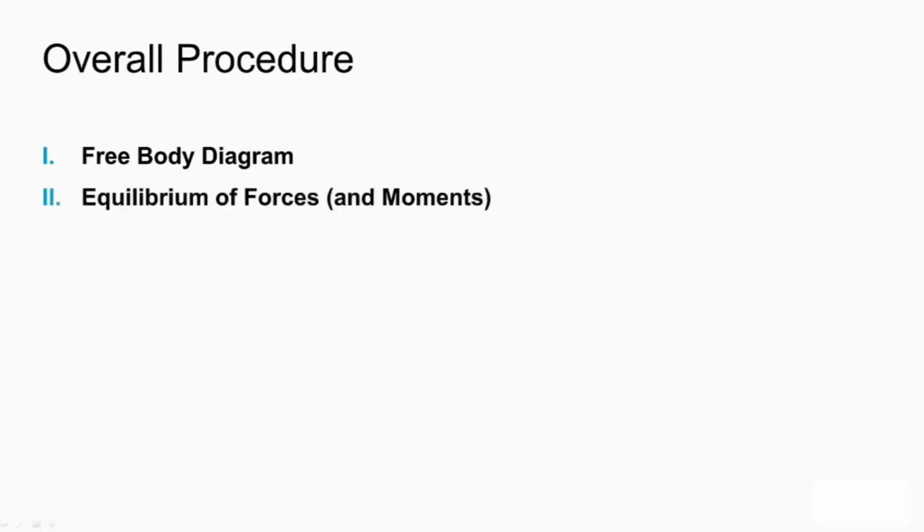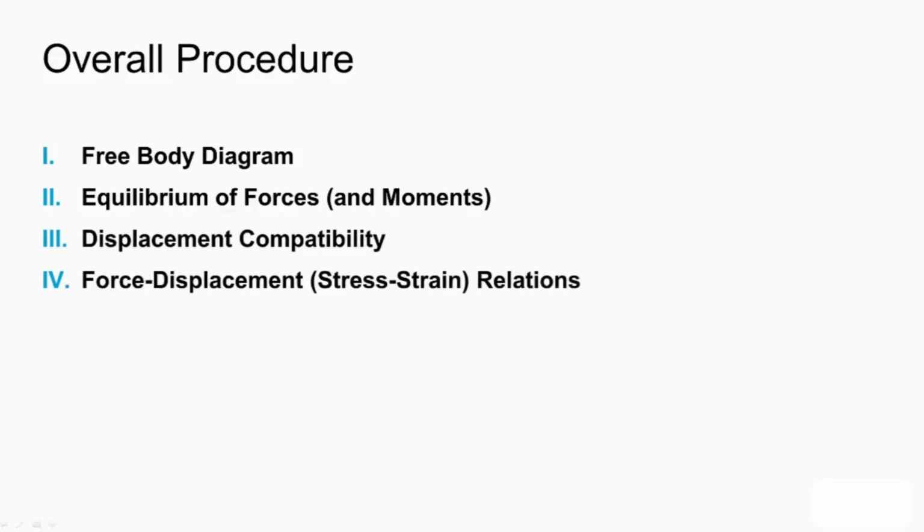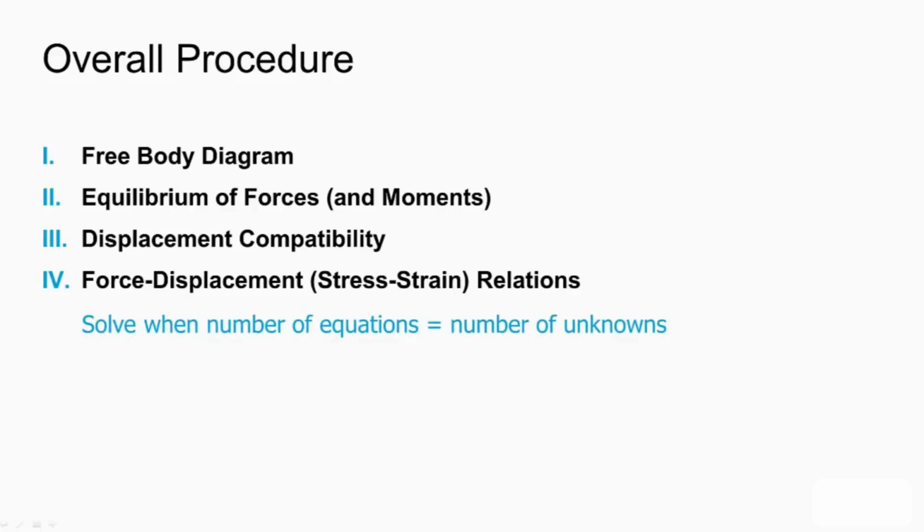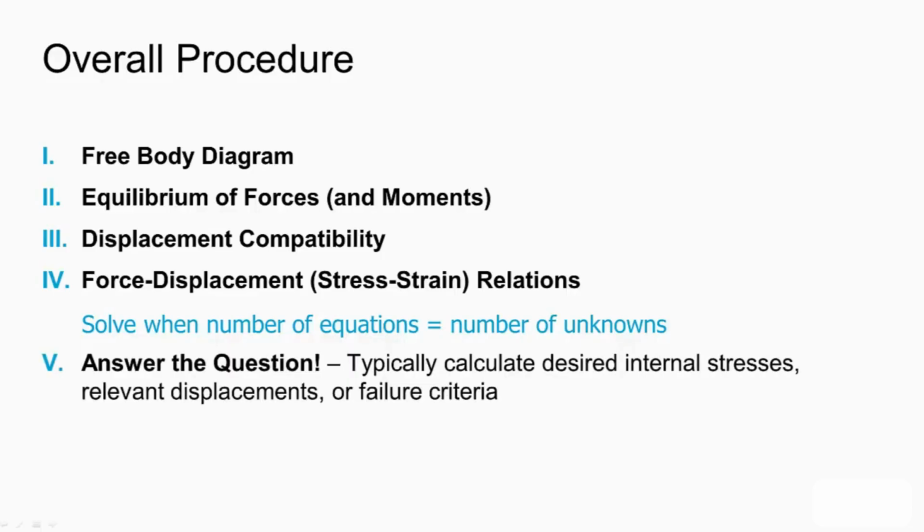The second step is always equilibrium of forces and moments, and this is where you find out if your problem is statically determinate, if you can solve for all your unknown forces and moments, or if it's statically indeterminate. You then have displacement compatibility and force displacement relationships to give you those additional equations you need in order to solve a problem. And once you have the same number of equations as unknowns, you can solve for your unknown forces. And then the last step is always to answer the question.